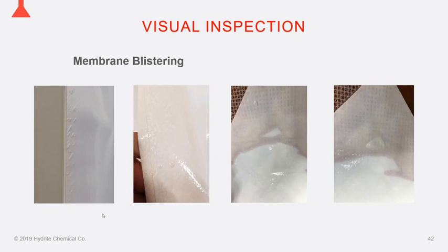And once they get in there, if they're near the glue line, they can't get out, and they act as an osmogen, so they pull water to them. And as they do this, they can just be water, which is not a huge concern from an inspection perspective, but the problem comes when that bubble increases and actually compromises the integrity of the membrane, and it starts sucking feed matter into there, and you start actually having essentially pus in your blisters, but it's just feed solution and the proteins involved. So a lot of companies have invested in blister-free membranes.